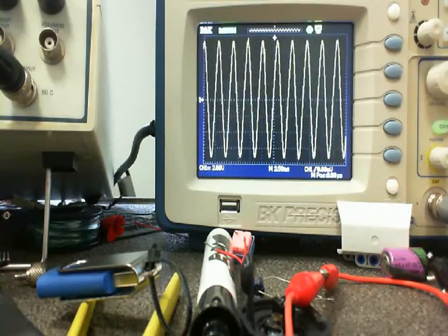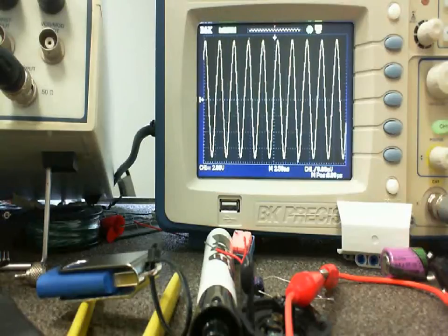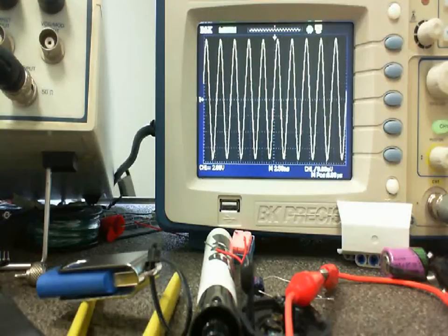Works real good in what? Digital. So if I brought it into a digital thing like a PLC or something like that, it'd be nothing, right? We could set up a counter, bring in this pulse that's coming off here, run it into a PLC counter, and then count those things over a certain amount of time, come up and give you the RPM, nothing at all.